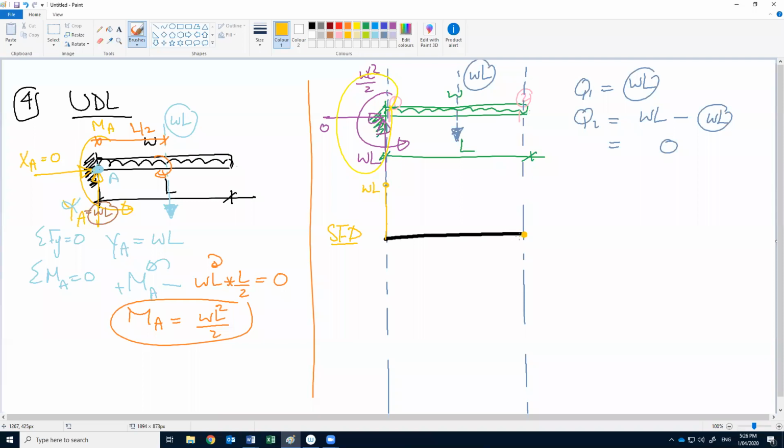How do we connect these two values? Straight line. We said before, if we have uniform load, the shear will be a straight line. What is the sign convention for this one? Positive, because it's shear: above positive, below negative. Okay, so now we can shift to the moment.